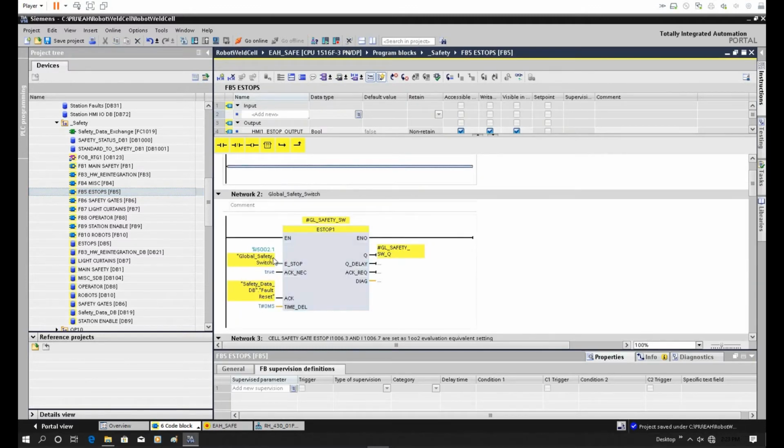For example, the e-stop switch, e-stop, and that is the output. And this e-stop input is already grouped by the hardware. So every time you program the e-stop, you just need to use the lower address. For example, if we use the 5000.0 and 5000.2, these 2 channels, you only need to use the 0.0.